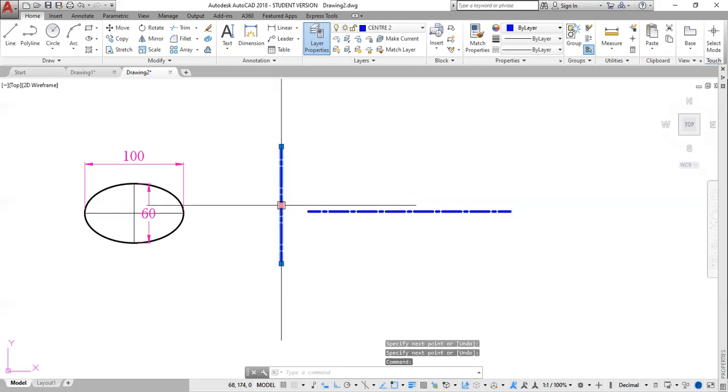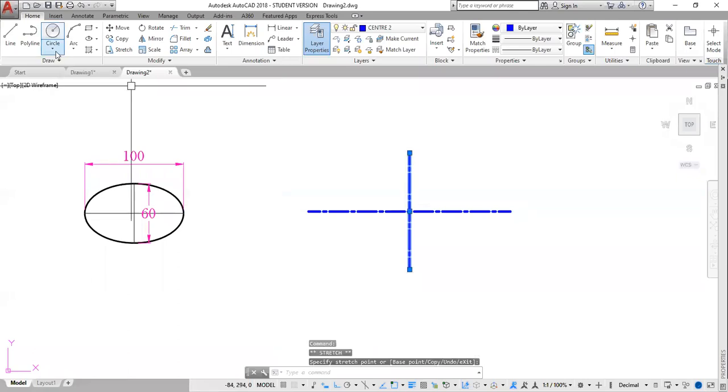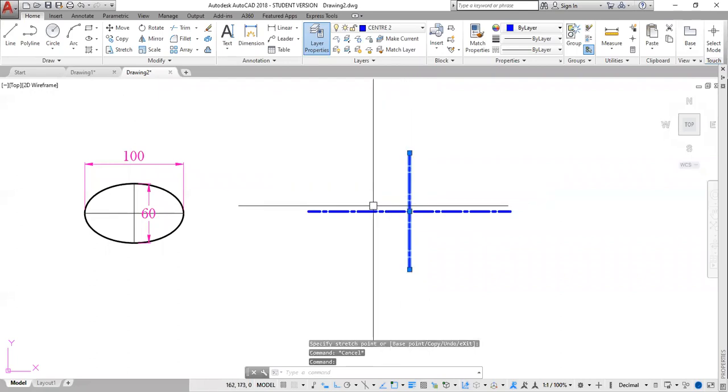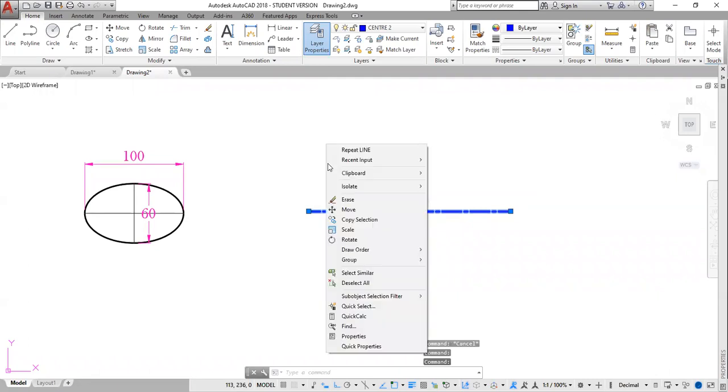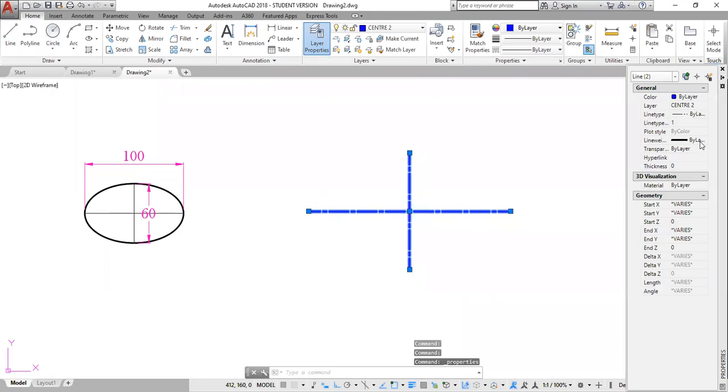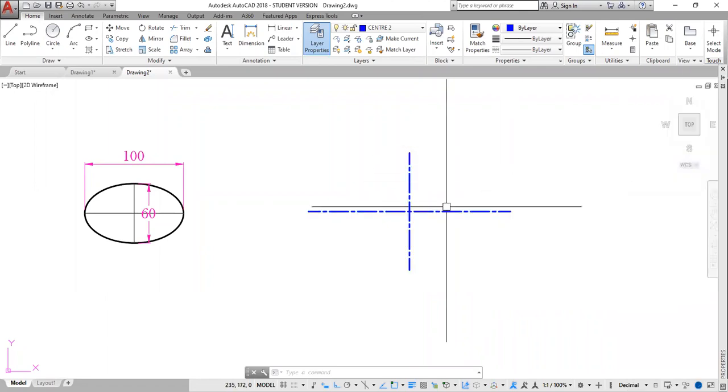Well, yeah, we're using the central method, so I click this there. These lines are way too thick, so I need to reduce the line weight thickness for those. So I'm gonna click here, go to properties, and change the line weight thickness to 0.3, which might be good. That's still a little thick, but it's okay.